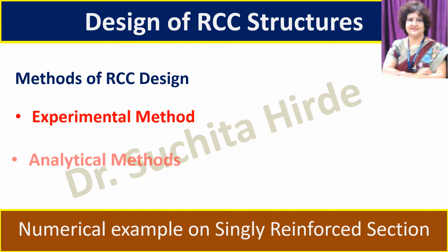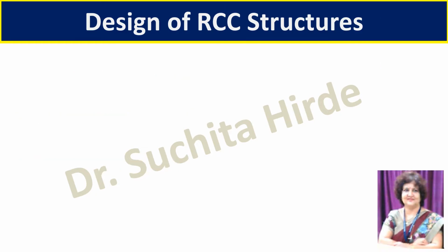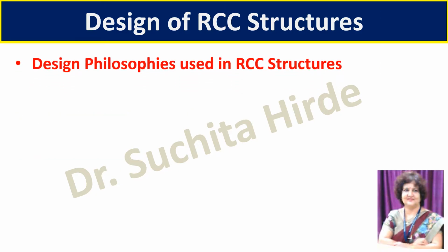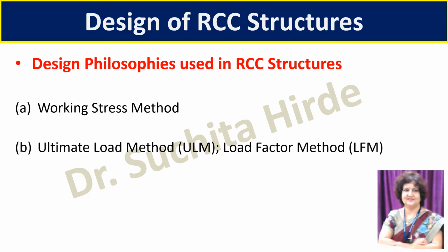Now these analytical methods are based on identifying failure criteria based on material properties. There are three design philosophies used in design of RCC structures, that is working stress method, ultimate load method, which is also called load factor method, and limit state method.